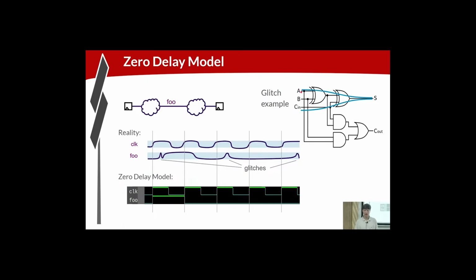So if, for example, these might be driven straight out of a flip-flop with similar timing, and maybe from one cycle to the next, the values of A and C transition. So the transition of A is going to propagate through this XOR to transition this, which is going to transition through this XOR and transition this. C is going straight to the second XOR gate and transitioning S.